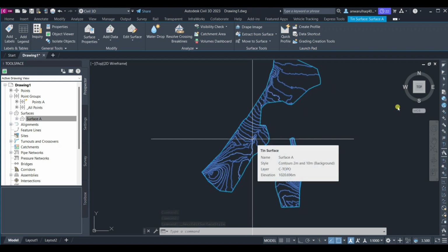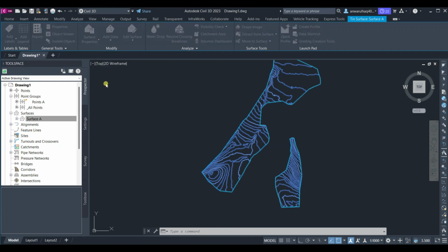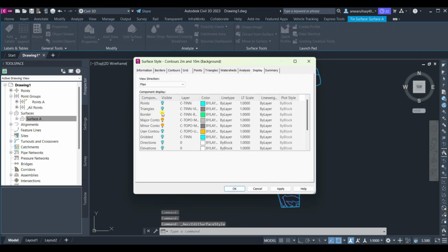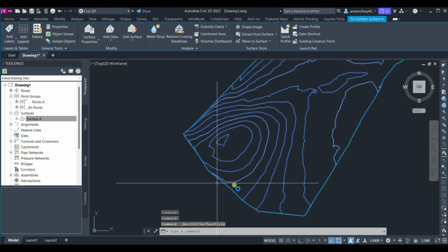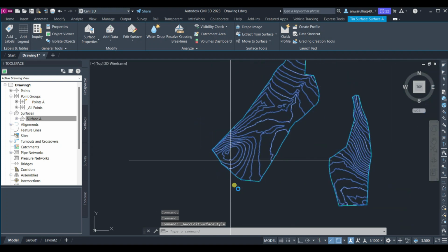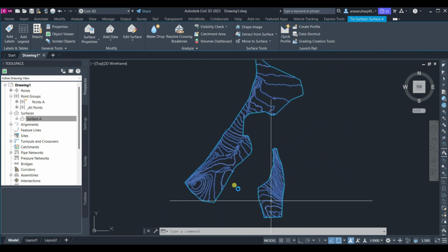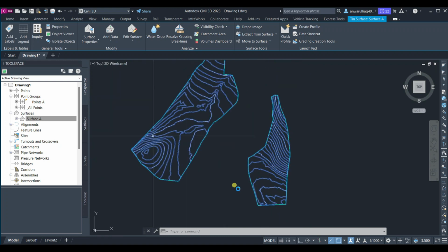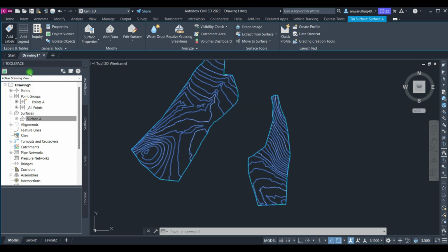Now actually civil engineers use this topographic survey with the topographic contour lines on it, major contours and minor contours, already okay. So I need to mention my contour labels on it. Actually these are contour lines, and I need to provide contour labels on them. Okay, so let's draw my labels. Keep your surface selected and go to add labels.